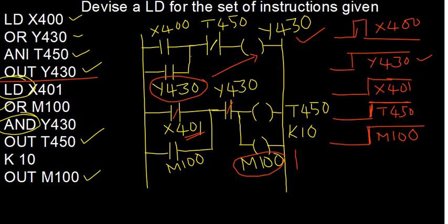So you can have your X401 also in a similar way, a momentary switch. So this is my X401. The sequence here, this instant, is at your discretion, right? The closure of X401 momentarily is only to activate your timer. X401 is only to activate your timer. So now, let us say that from here to here you have got a 10-second timer. Okay, so up to here.